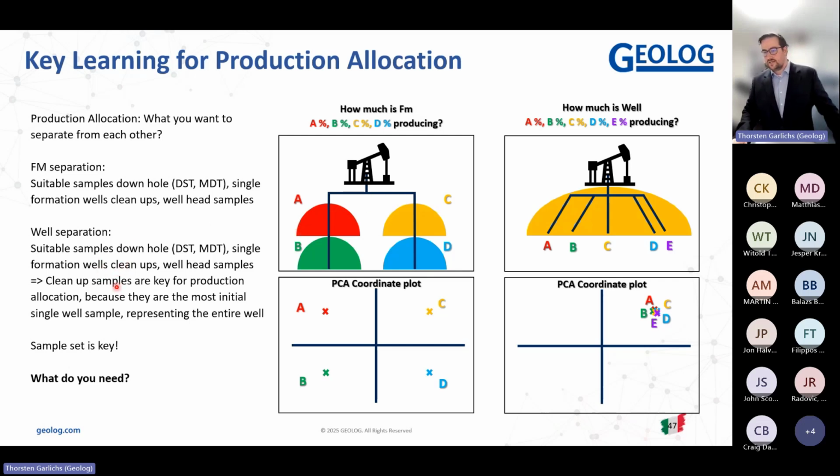But when you would like to do a well separation, like in the Maria case, here we also have some suitable samples, and depending on your setup, DSTs and MDTs are not so suited, for Maria at least. We always recommend using cleanup samples because they are the very initial production you normally take when your entire development well is drilled and you produce the first oil. So the sample set is key, what type of samples you can take. When you are in any development phase, please remember that potentially in the future you would like to use the oils for production allocation.